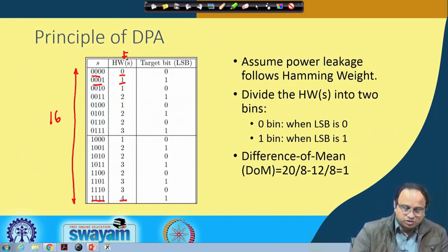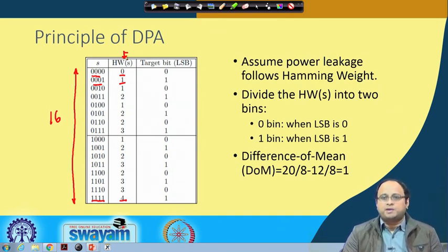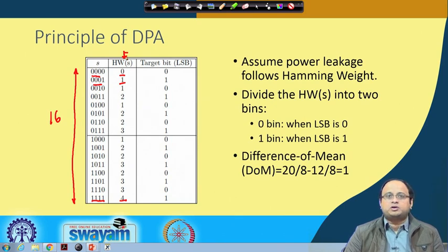So, why do I observe the Hamming weight? Because in VLSI there are different power models. The objective of a power model is to get a hypothesis of the power. Of course, power consumption is a very complex manifestation of several things, but what has been found is that a major contribution comes from the inherent encoding of the state. There are different power models like Hamming weight and Hamming distance, some of which we will see as we progress in the class.